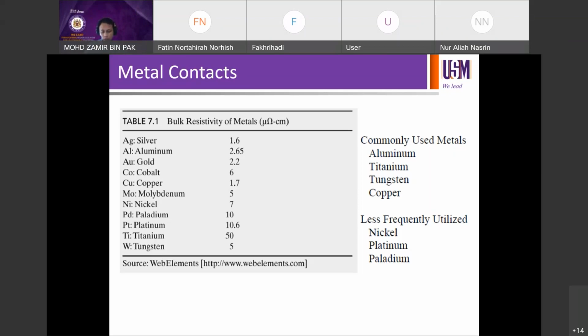in micro ohm cm. So when we talk about resistivity of silicon last time, we discussed the resistivity against doping level curve. If you can recall, we discussed a couple of times. The typical magnitude of the semiconductor resistivity is usually in the milliohm region ataupun ohm cm punya region. But if you talk about metal, we're talking about micro ohm. Okay, micro ohm.